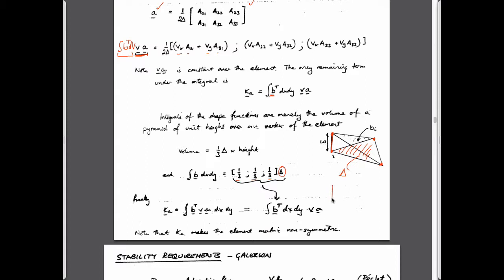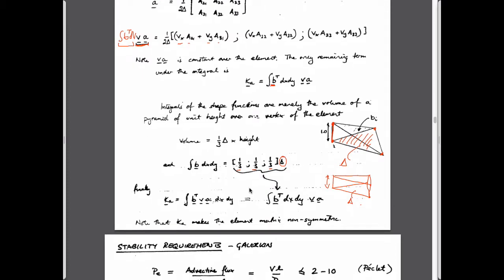So if you take your triangle and you have a height of that triangle being this, if you added those shape functions together, it would just give you this planar surface on the top of height 1 and the area of the triangle in area. And so it's just a matter of splitting that up to link it between each of these individual components. Nothing more than that. And so we can develop the triangular element by doing that.